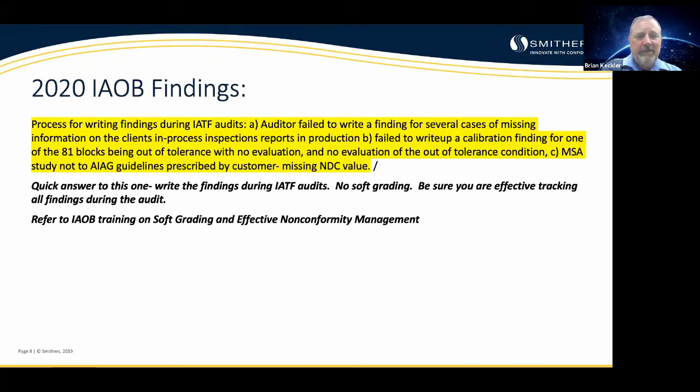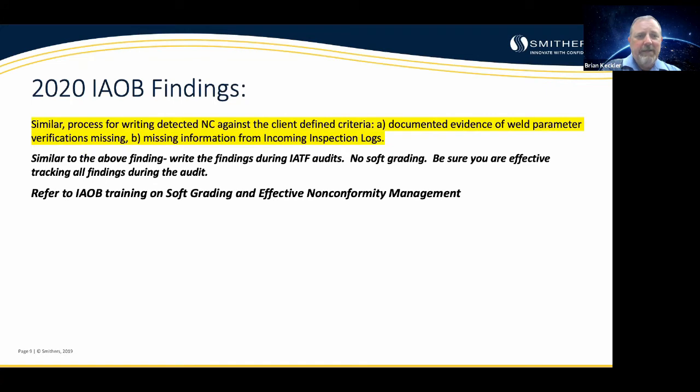If you go to the next slide as well, a similar finding: the process for writing detected nonconformities against the client's defined criteria. There were some issues specifically with lacking evidence of the weld parameter verifications and missing information on the incoming inspection logs. So these both came within the same audit. They were very similar findings, and our response to both of these were pretty much the same.